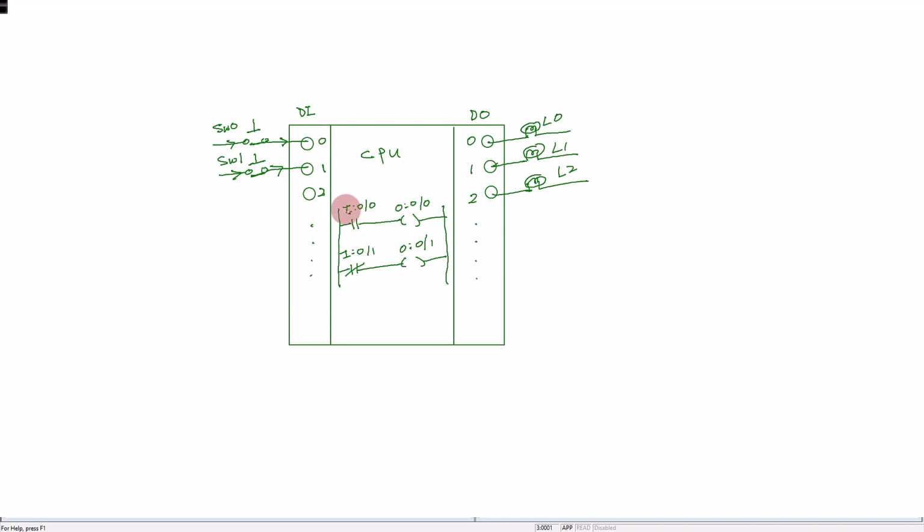is this virtual switch bit 0, which is linked to this input terminal 0. This normally open virtual switch will trigger from normally open to close. Thus, the actual, sorry, the virtual. Remember the keyword virtual. I'm not talking about actual. This is virtual since the programming exists in the memory only. This switch and this output coil are just virtual. It exists only in the program, not in the physical device.